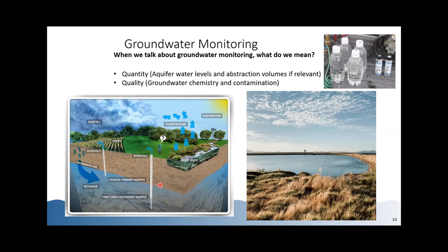The water level within the borehole is related to the volume of water that is stored within the aquifer. And so by monitoring the water level of the aquifer, of the borehole, we're able to assess aquifer depletion, aquifer recharge, how the aquifer is responding, how the borehole is responding to abstraction. In addition to that, Kes also touched on some of the water quality requirements. And yes, we also want to monitor that, because water quality can change.